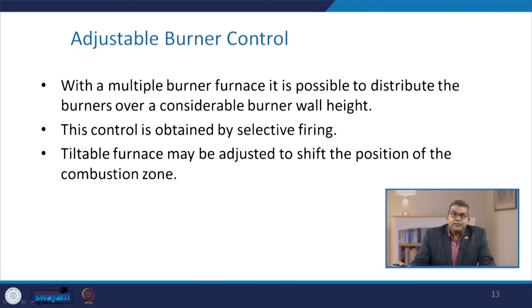Another important aspect is the adjustable burner control. Sometimes in the furnace we use multiple burners for maximizing the efficiency. So, with a multiple burner furnace, it is possible to distribute the burners over a considerable burner wall height. Now, this control is obtained by selective firing.